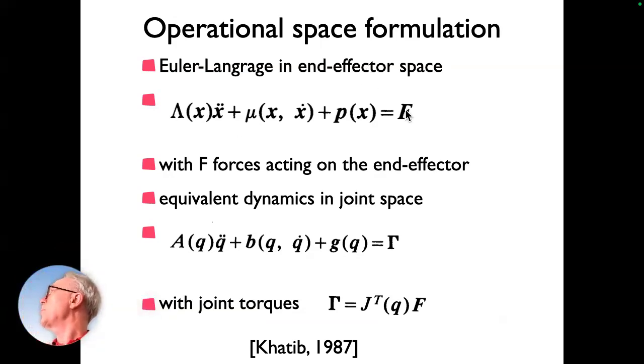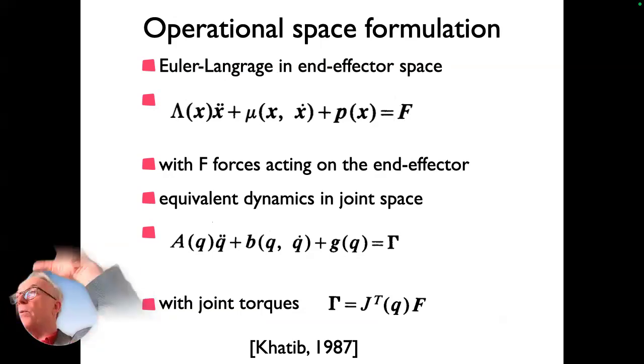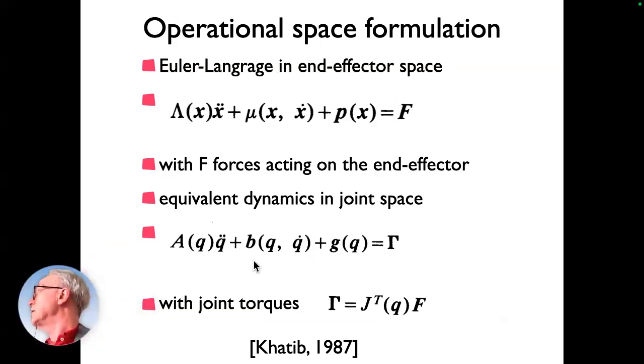And these would be the kinds of forces that act on your hand to bring about the movement. And if you have that formulation, you can now describe what kind of impedance your hand has in the world. The relationship between those two can be figured out mathematically. You can actually write down these matrices if you know those, and vice versa. For instance, the forces and the torques are connected through this form, the transpose of the Jacobian, which you encountered earlier. Again, I don't explain that in detail, but that's one step you have to do to bring in desired properties of the hand in space.